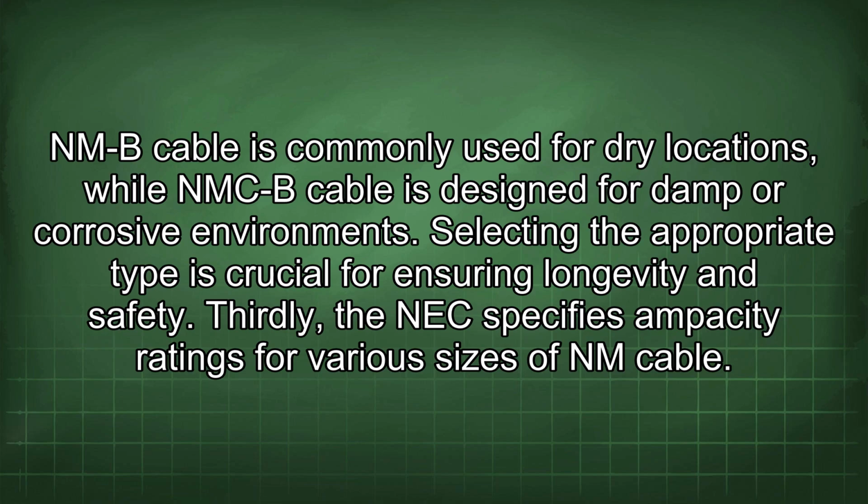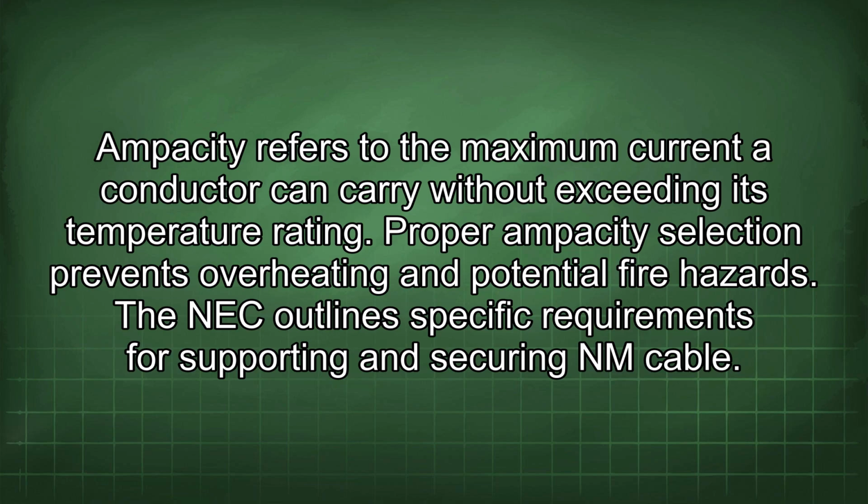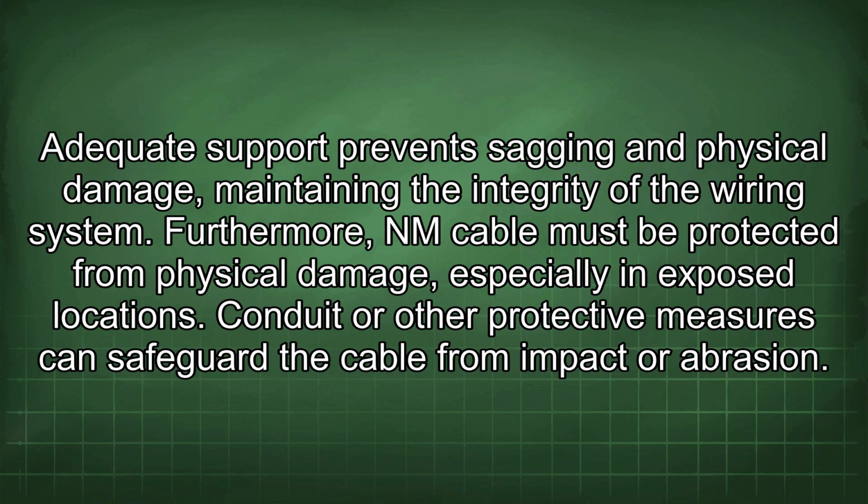Thirdly, the NEC specifies ampacity ratings for various sizes of NM cable. Ampacity refers to the maximum current a conductor can carry without exceeding its temperature rating. Proper ampacity selection prevents overheating and potential fire hazards. The NEC outlines specific requirements for supporting and securing NM cable. Adequate support prevents sagging and physical damage, maintaining the integrity of the wiring system.